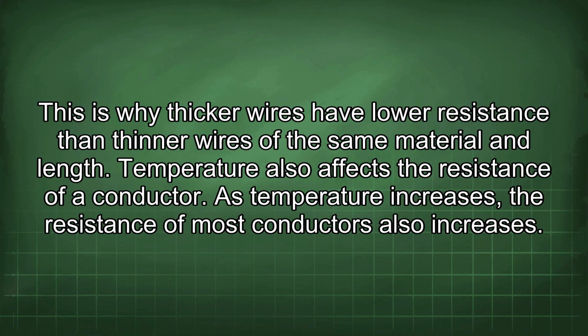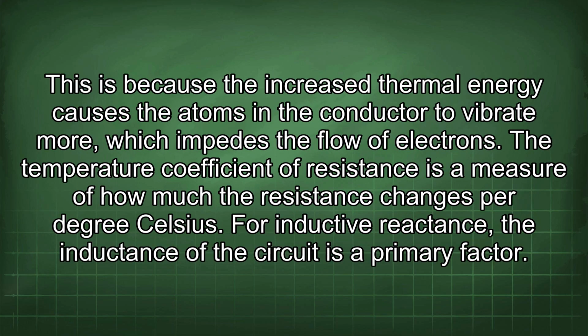Temperature also affects the resistance of a conductor. As temperature increases, the resistance of most conductors also increases. This is because the increased thermal energy causes the atoms in the conductor to vibrate more, which impedes the flow of electrons. The temperature coefficient of resistance is a measure of how much the resistance changes per degree Celsius.